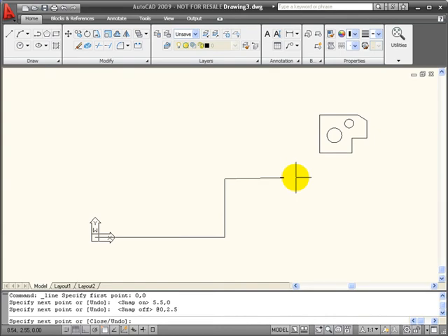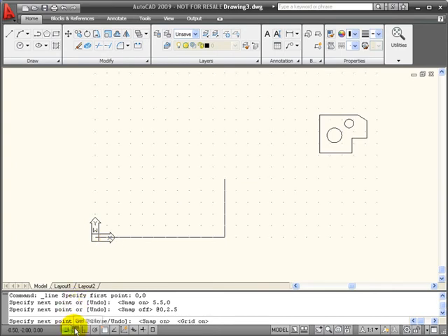Now I'm moving to my right, and we're going to get some help from our drawing aids. We're going to turn on the Snap and Grid down here on the status bar. Also, by watching my drawing coordinate box down here in the corner, I can see that as I snap across, the snap is currently set to 1/2 unit. When I come over to 8 and 2.5, I'm going to click the mouse and accept that location.